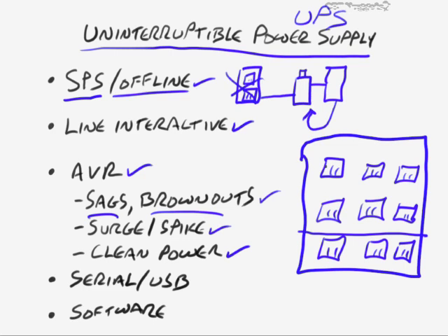So these just have pass-through power, so that it would just go through the UPS and on into this electrical power over here. It doesn't really receive any power from the battery at all. It's just pretty much the same as using an extension cord from the wall outlet through the UPS to the computer if I were to use one of these. And it'll be marked on the back of these where you plug things in. And then the other ones would be protected, and they'll often say protected.